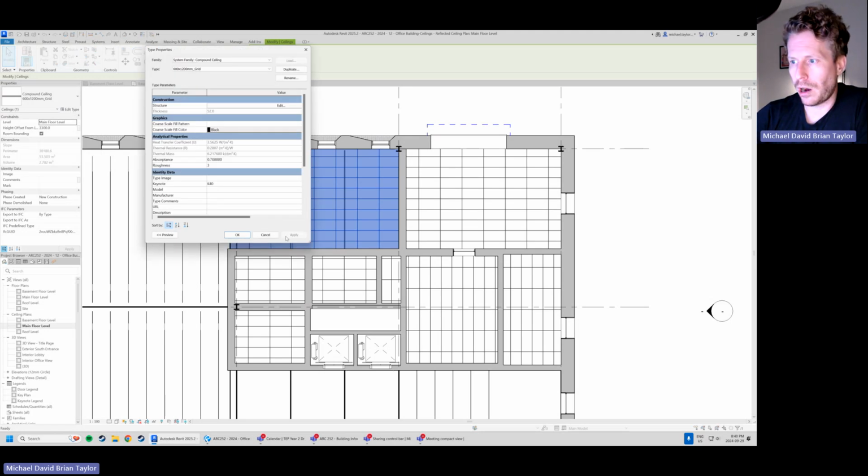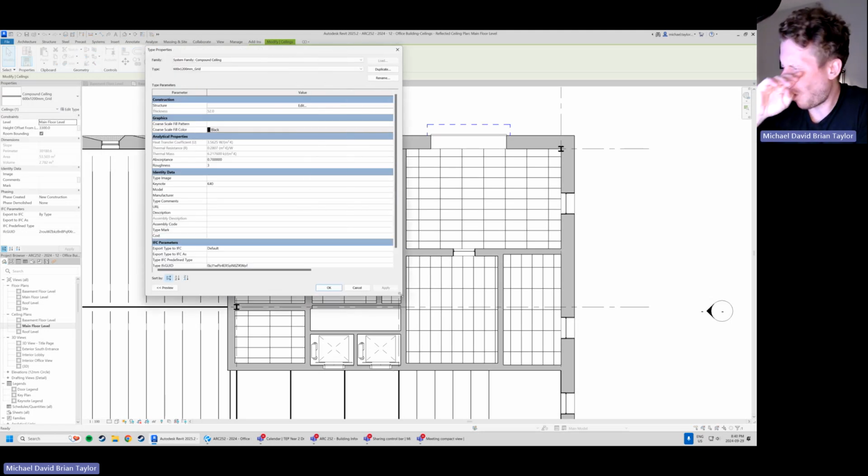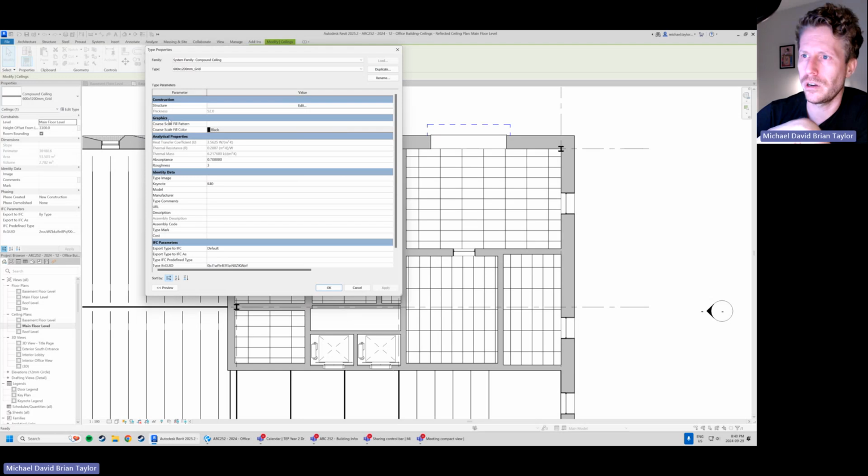Very similar to our wall tool, our roof tool. You might see some pretty familiar pieces here. We've got structure, right? And this is really where we would go to edit our overall ceiling thicknesses. So ceilings, of course, also have assemblies. For the purposes of Best in Town, we're not going to edit any of the structures themselves, but I want you guys to see that you do have the ability to come in here and modify some of the thicknesses of the components of the ceiling itself.